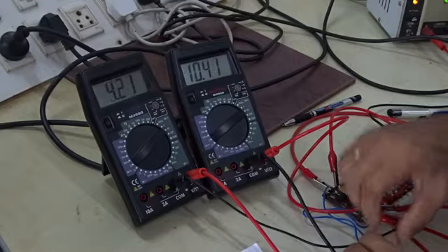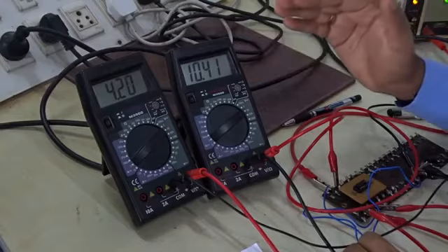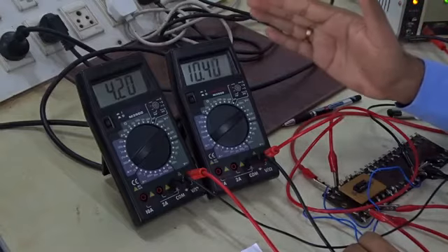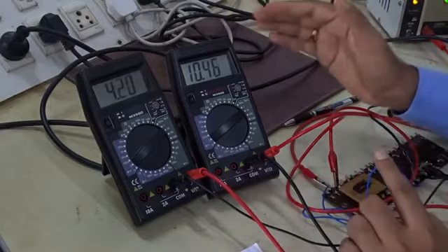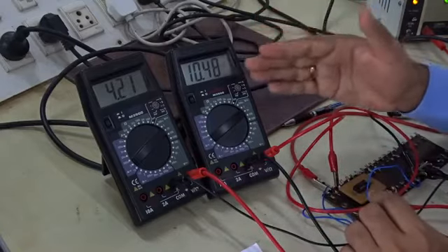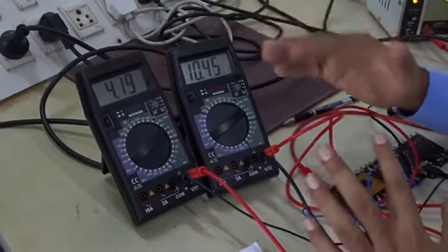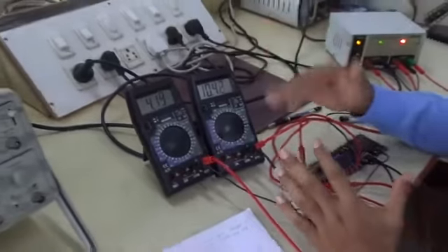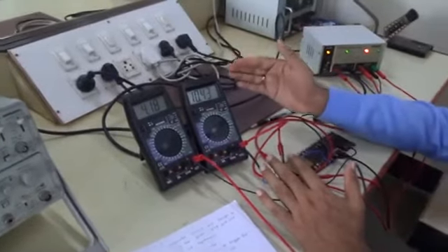You can observe here, if the voltage is less than 5 volt, you are getting plus V saturation, around 11 volt. So when Vin is greater than 5 volt, we get minus 12 volt. When Vin is less than 5 volt, we get plus 12 volt. So this is just a comparator. It's comparing the voltage at the inverting terminal and the non-inverting terminal.